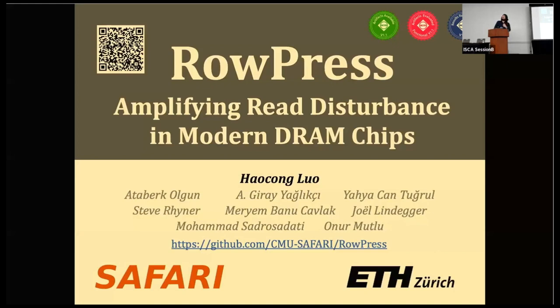Hi, nice talk. I'm Irina from Apple. A few questions. First is, what causes RowPress? While our paper is under review, there is a concurrent work put out by some engineers. They basically explain there's a device-level effect called the passing wave effect that attracts electrons from the victim cells. This effect is very significant when you keep the aggressor row open for a long time. And we believe that could be one of the device-level mechanisms that cause this kind of thing.